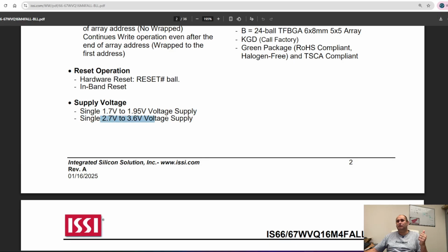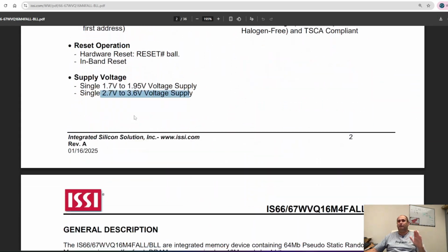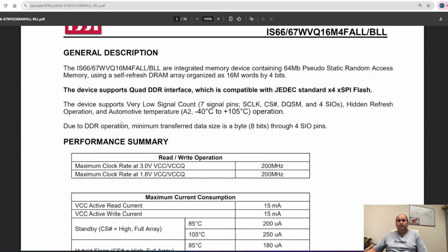So the 3 volt version of this part will work just fine at 3.3 volts. So I added the regulator for nothing. I'm going to bypass that regulator. Now I built boards with a regulator, but I'm just going to bypass them on the PCB, on the first set of PCBs. So yeah, look, first mistake, yay.